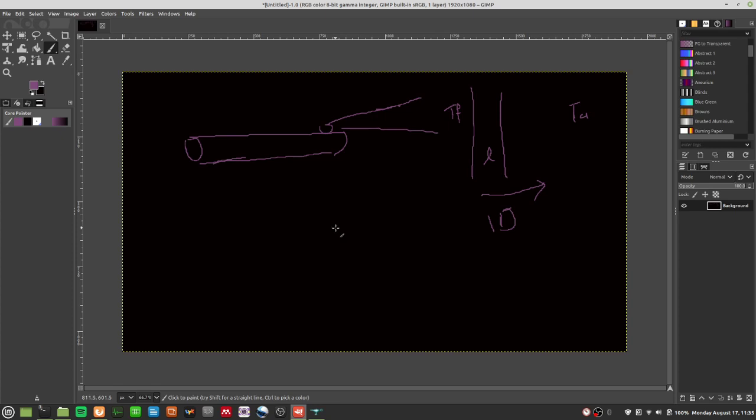Now, if you have these two extended pipings here, for example, and you have some insulation here and some insulation here, and you apply this same boundary condition throughout this curved part on top, you'll be treating this part as a 1D case.